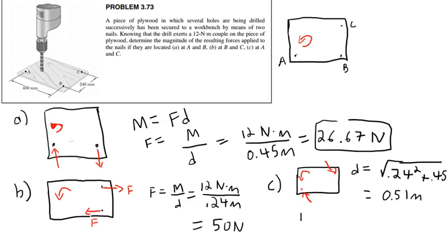And then the force is going to be equal to M over d, 12 Newton meters over 0.51 meters, which will come to 23.5 newtons. 23.53 newtons.